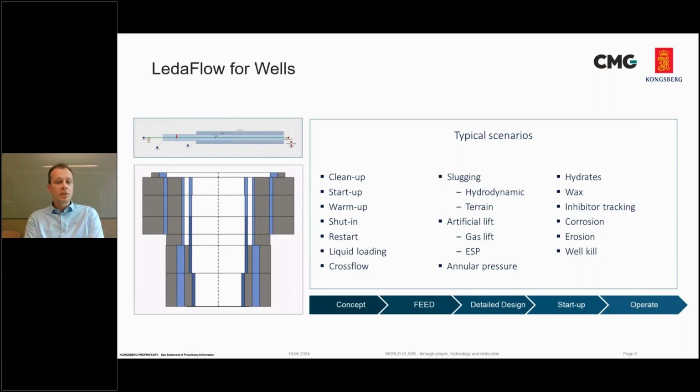You can use that for gas lift, but also for well integrity management, looking at the pressure in the different annular spaces as the well heats up and cools down. And then you can do different scenarios like well cleanup, warm up. You can look at slugging, artificial lift, and many other flow assurance disciplines like hydrates and wax. And all of those scenarios we can simulate all the way from concept selection to the operation stage.